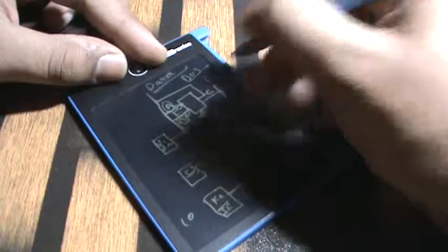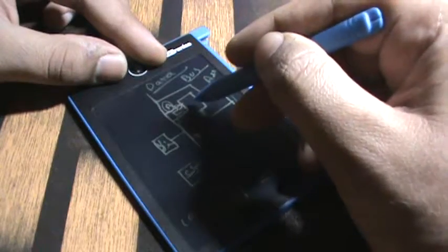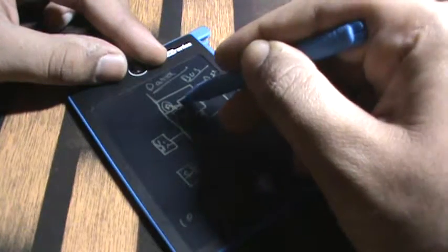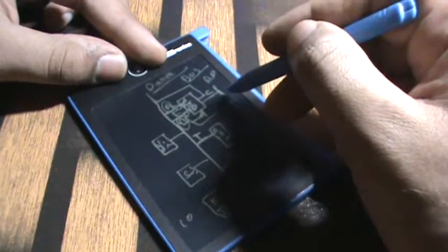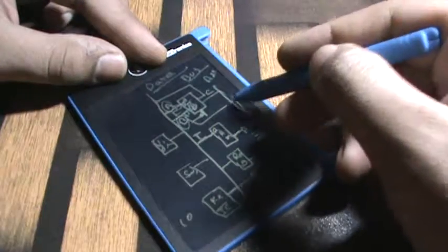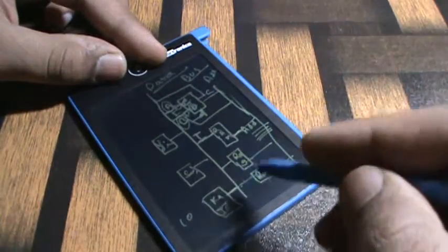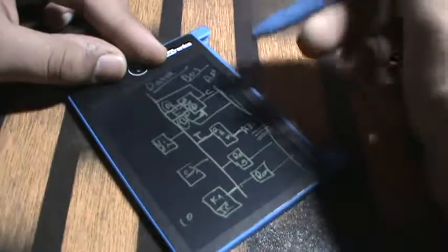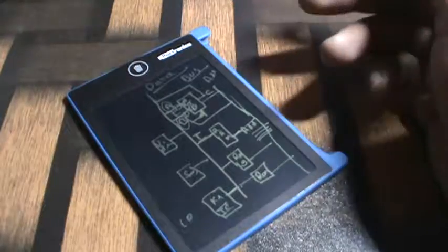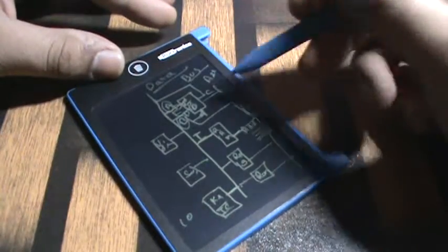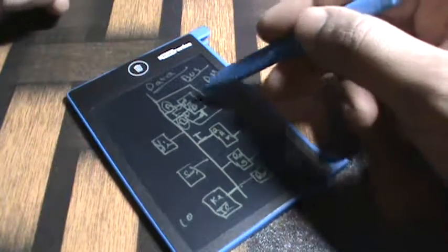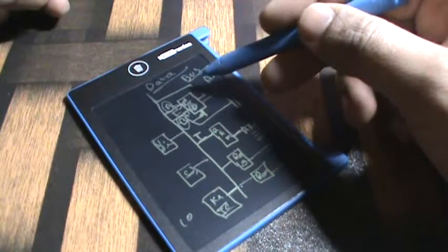So this is an address bus, and the processor or the CPU is going to set some value on the address bus, which decides which particular component to address. We are going to discuss how address decoding works, but this address bus is again going to be an 8-bit number which is set by our CPU itself.